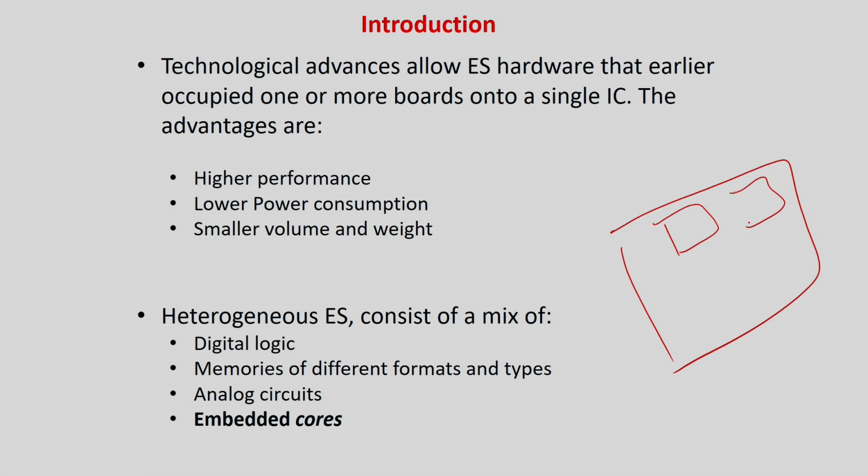So I have 4 modules. Let me assume that this is my entire die. These are the two IP cores which I purchased from the market. Cores are also simple hardware designs; they can be at the gate level, register transfer level, or layout level. And two I design; these are my designs. So I design these 4 blocks in one die and send it for manufacturing. For my own blocks I have full control, I can put my DFT circuit etc. But for the IP blocks I do not have much information, because they have been sold to me by the vendor.